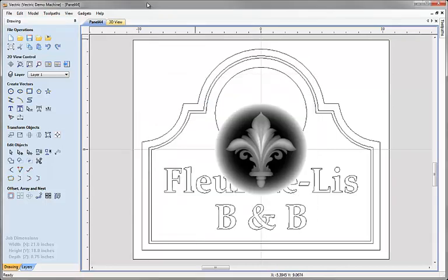When we import a 3D toolpath, two things happen. The first is the software generates this grayscale preview that you can see in the 2D view here, showing me the size and position the toolpath was calculated in VectorArt 3D Machinist or Cut 3D. This grayscale is actually something that we can select and move around in order to change the position that the toolpath is going to be cut within this part.